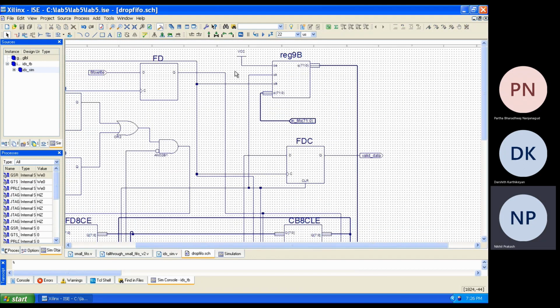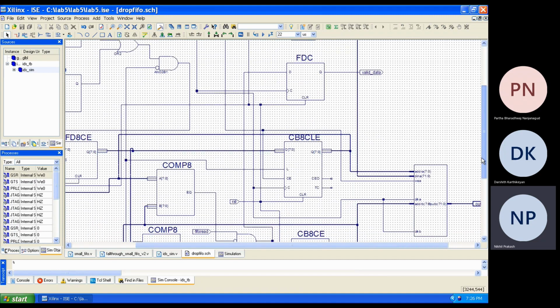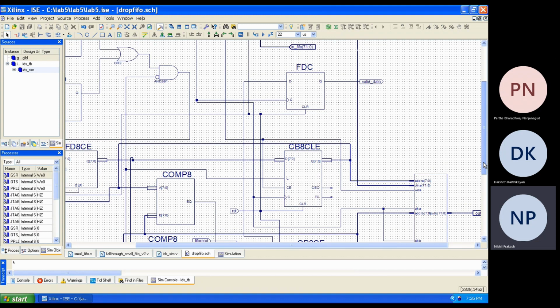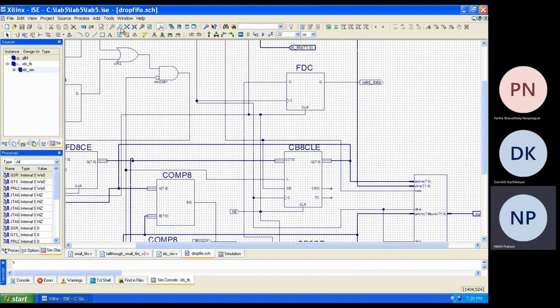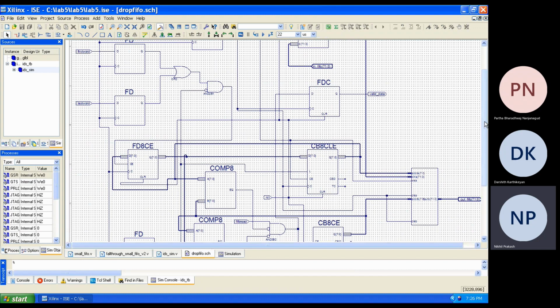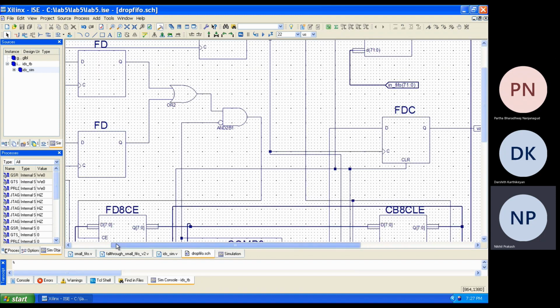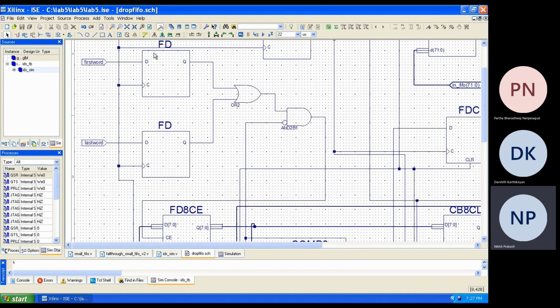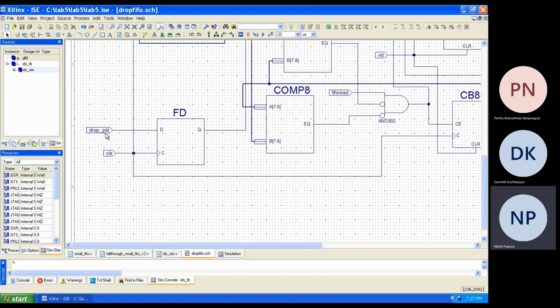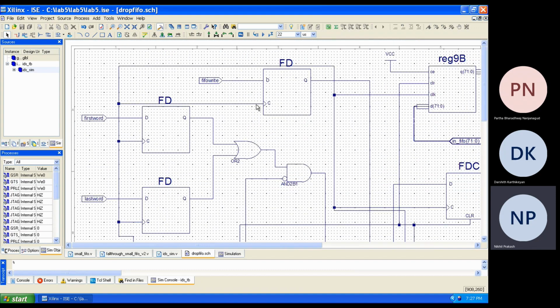So that's coming, but we don't feed that data directly to the port memory, right? Instead, we're going to send it in a controlled manner. Every time you have a packet of data, it contains a lot of words. Whenever the first word arrives, it triggers this first word control signal here, with appropriate qualification. When I say appropriate qualification, I mean the drop_packet control signal is not high. If that is not there, we let it go through. So you can see that.